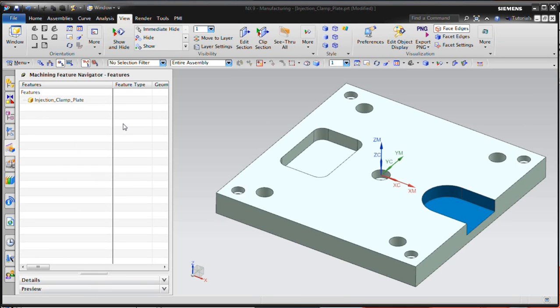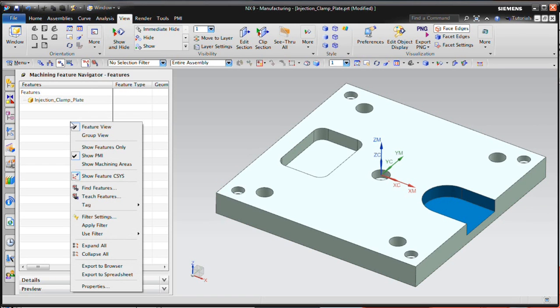Now let's add more capability to our ability to process and identify these features. Here we'd like to identify features only of a certain color. So if we had parts where some of them were perhaps requiring a higher tolerance or something, we could color those, and if that was part of our process, we could identify those particular features separately. So I've already got this one colored as strong azure. Let's go ahead and show you how to teach that feature and put the color identification into that definition.